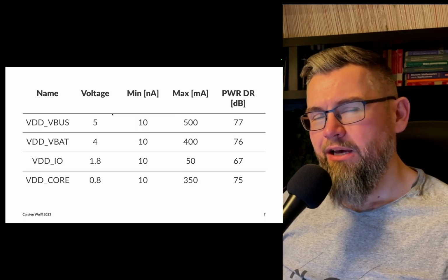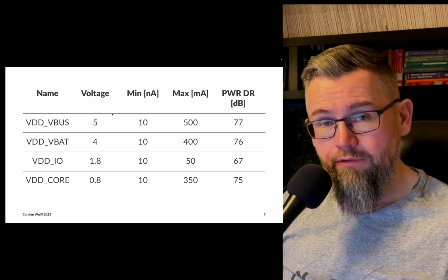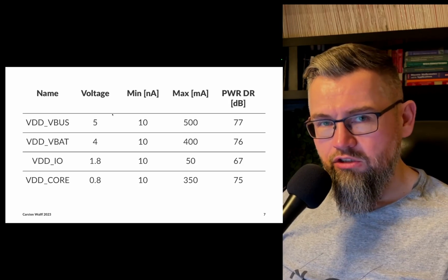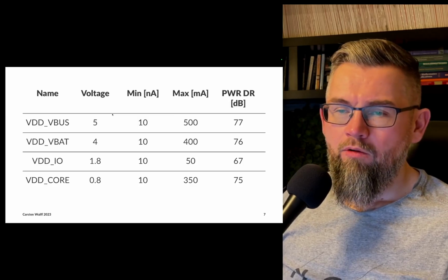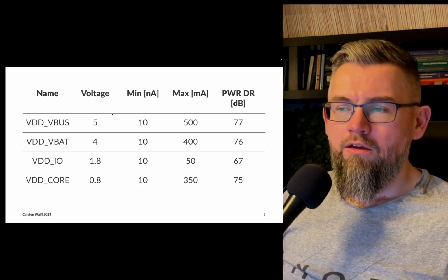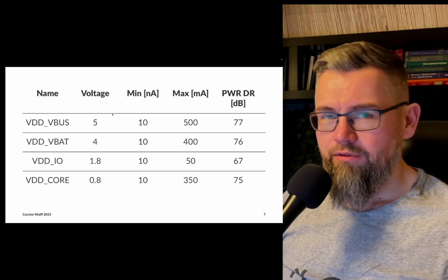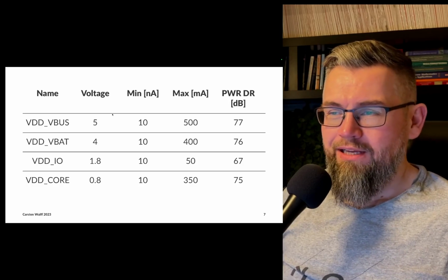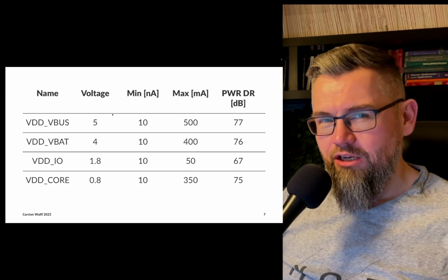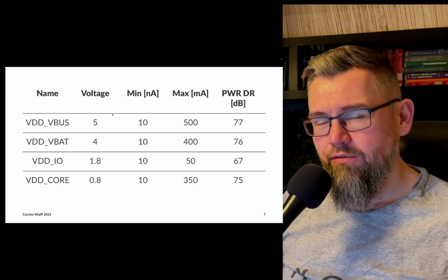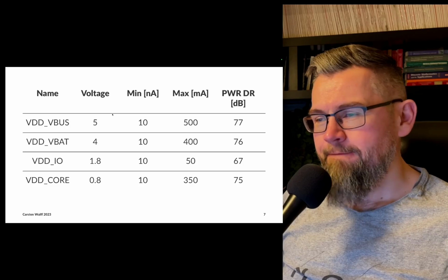Now, maybe the battery has an inherent self-discharge current of maybe a microamp or something, or maybe it doesn't. It depends on the chemistry. Anyway, if you want to approach a really good number, I think today not many chips can go down to 10 nanoamp leakage when off. That's pretty hard.